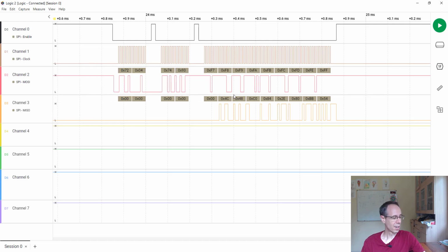It's always good to have a logic analyzer to see this, and sometimes it's better to control it by yourself, so that you know what's happening. This was an introduction to SPI and Zephyr, a little bit more detailed here because the sensor is quite complex to control, and you saw that it's sometimes not so easy to control such a sensor and send the right commands. The BMP280, BME280 and BME680 work quite similarly, so if you understand this sensor, you will also understand the other ones.